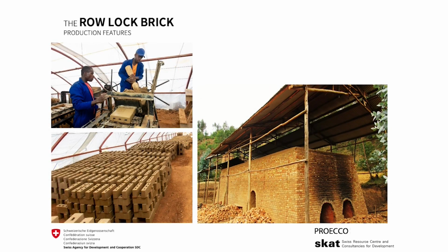As mentioned earlier, the brick manufacturing happens in a controlled environment, where the raw materials are mechanically extruded, properly dried and fired. The firing happens in a kiln where temperature and time are constantly monitored. The perforations within the brick body allow the heat to reach the brick core, ensuring an evenly fired product.